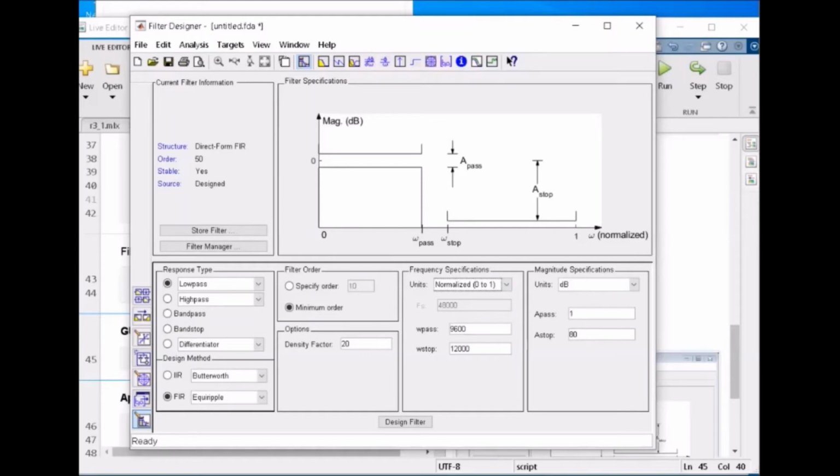The physical meaning is that to understand something about the signal, we need at least 2 samples per period. This way we can estimate the frequency or another characteristic of the signal, no less than 2 samples per period. Now, when normalized, we can tell where we need to stop the filter.